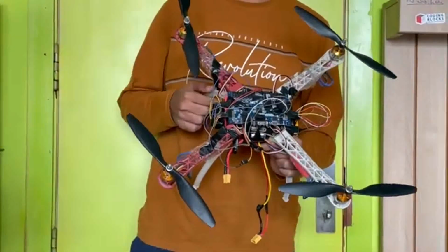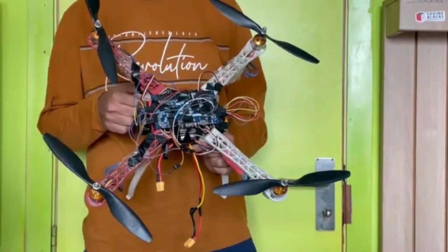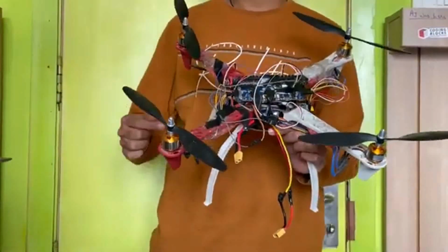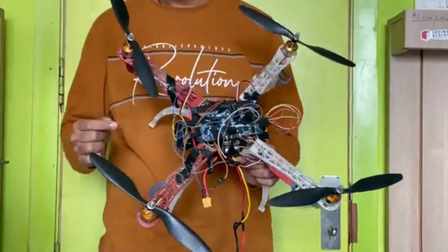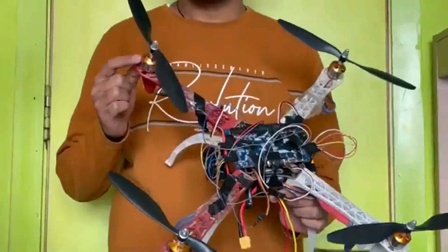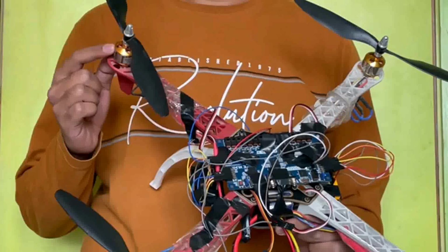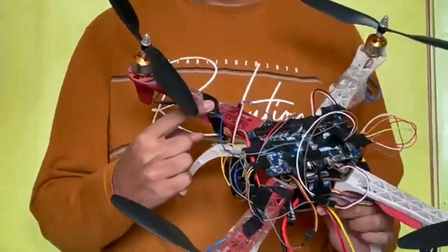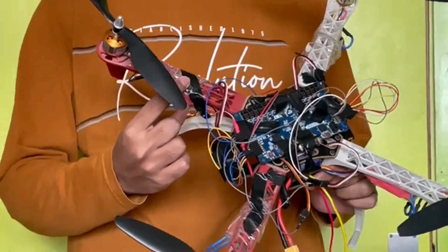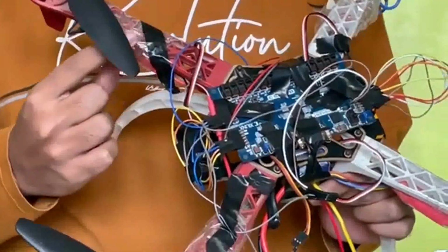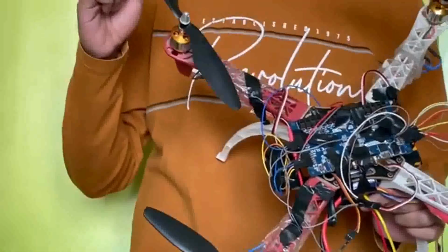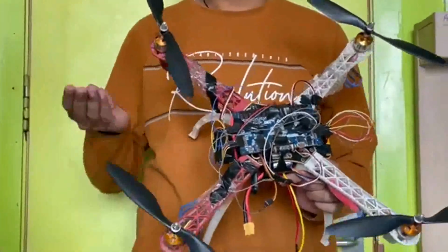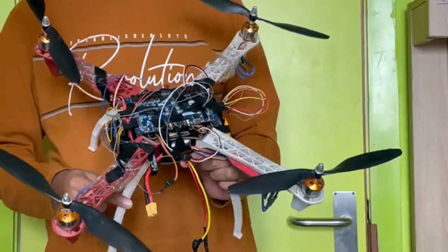Now we start with the hardware setup of our quadcopter. First we have a frame and a support for the frame which is used to prevent the components in cases of crash landing. Then we have the motors. These are A2212 brushless DC motors with a rating of 1400 kV. Then we move to the ESCs. These are electronic speed controllers that can drive the motors that have a current consumption of up to 30 ampere. Then the propellers. These propellers along with the motors are used to generate a thrust which helps us in lifting our quadcopter from the ground.